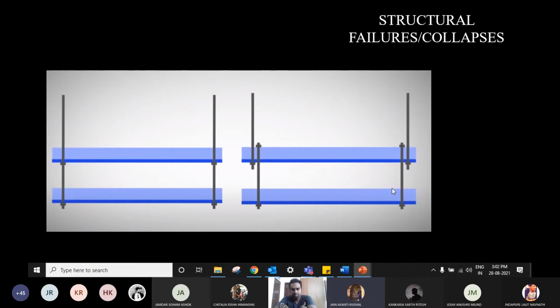Adding to what Anushree said, because the upper walkway is getting pulled below because of the load of the lower walkway, there's much more load that the lower connection has to take. Yeah, you're right. That's the reason. So what happens is, because of this kind of arrangement, this particular tie rod or the hanger rod in the second case is now carrying the weight of your lower walkway, and in addition to that, that load is being transferred to this nut.